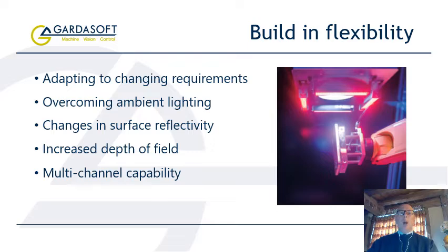Making use of overdrive mode for LED lighting offers even more flexibility without requiring hardware change. Operating in continuous mode, the controller can be set up for any inspections requiring light intensity up to the 100% of the LED rating. However, since LEDs can be safely overdriven at up to 10 times the maximum rating in short pulses, a much wider range of components can be inspected with existing hardware by utilizing Overdrive.